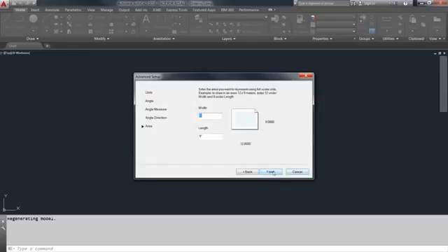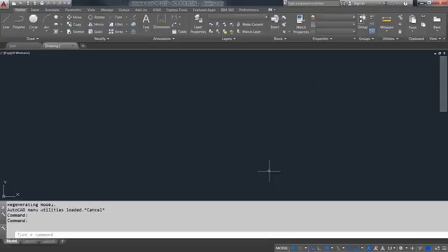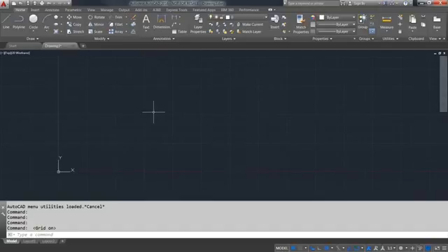The wizard is a little bit of a legacy. It's from the far prior versions of AutoCAD, but it's been kept in the program just because people like it and they're used to it and familiar with it, so we'll keep it in there. So now that we're done through the wizard, now we're in our drawing setup. And you notice that on this drawing, it doesn't have the grid on by default. Most of the newer templates are going to have the grid display turned on by default, and that is a drawing-specific variable. So you could have one drawing that doesn't have the grid, one drawing that does show the grid. That's drawing-specific.